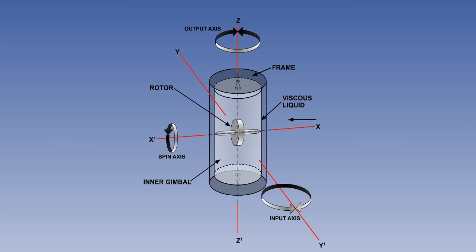The rate integrating gyroscope is a single degree of freedom gyro using viscous rather than spring restraint. However, the details of its construction need not concern us. We should simply note that, although mechanically it is a single degree of freedom system, because of the integration process, its output behaves as though it were a 2-degree of freedom system.